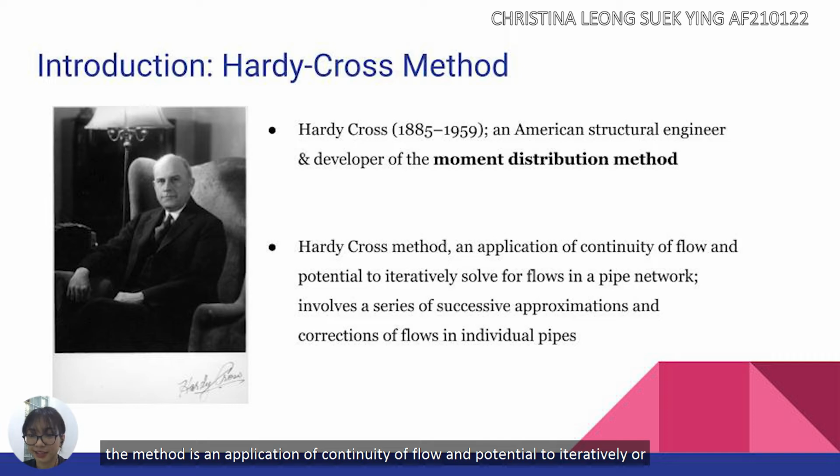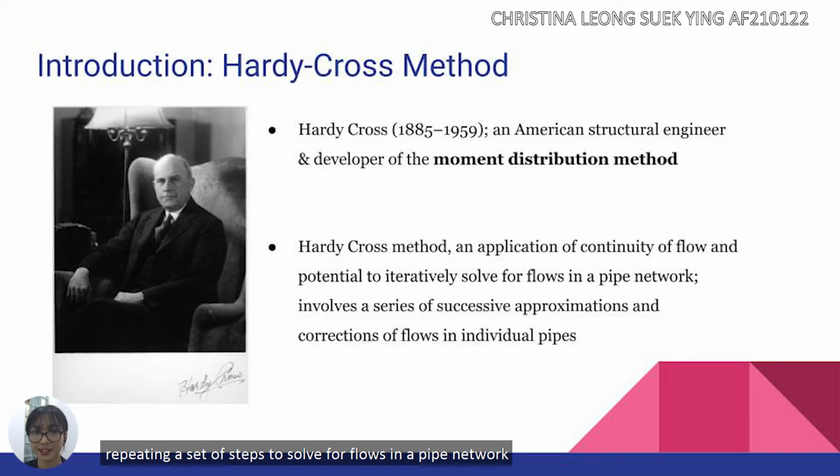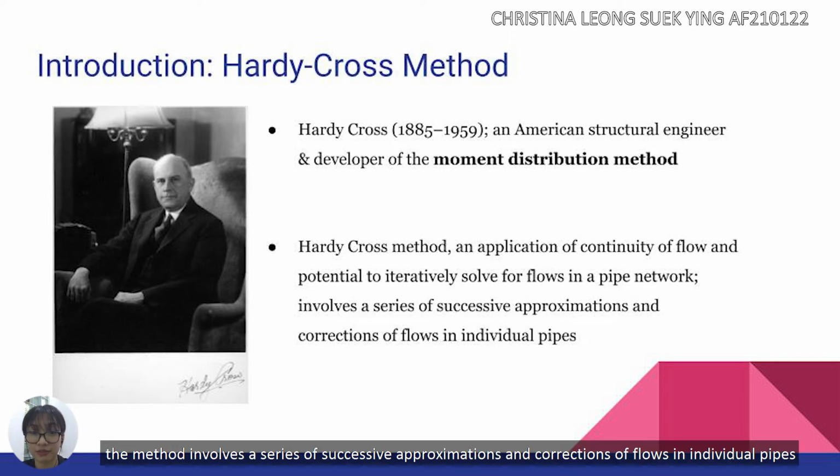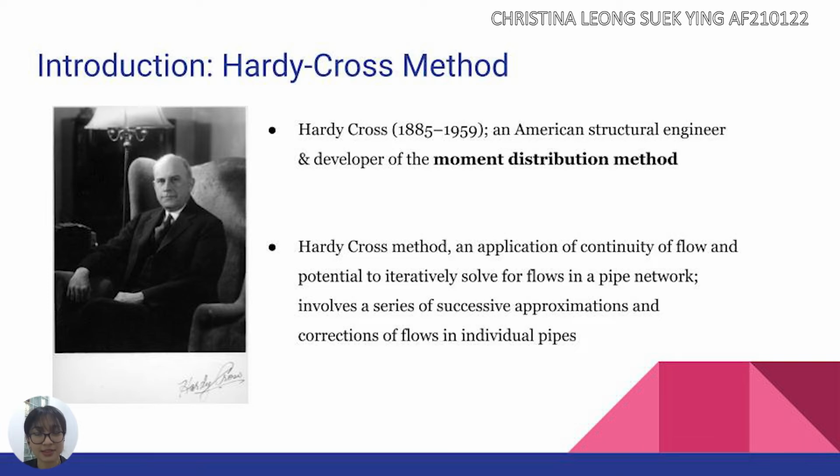The method is an application of continuity of flow and potential to iteratively, or repeatedly, apply a set of steps to solve fluid flows in a pipe network. Or a better definition taken from Madam Aliza's lecture notes, the method involves a series of successive approximations and corrections of flows in individual pipes.